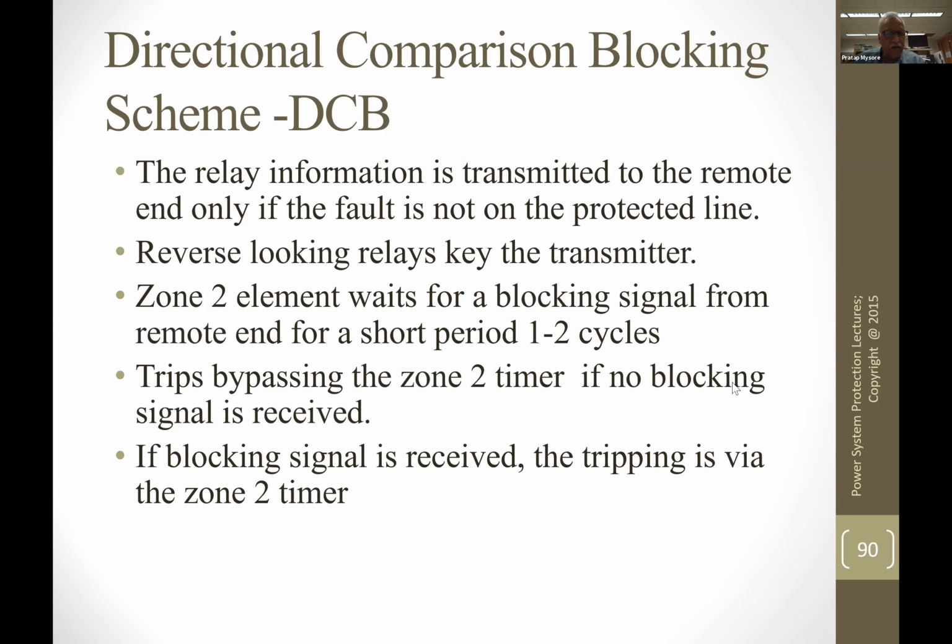In case you lose a carrier device, you do lose communication, and then you will get delayed tripping in other cases. But most of the time it is DC inside, and we don't have a UPS inside a substation. On loss of AC to the charger, the batteries are designed to last at least 8 hours, or 8 to 12 hours, depending on the philosophy of the substation owner, who can put in a second set of batteries as redundant batteries. At least one half of it will be working because the load is less, so it might stay for a longer time, or they are oversized so that they can stay without charging for more than 8 hours.